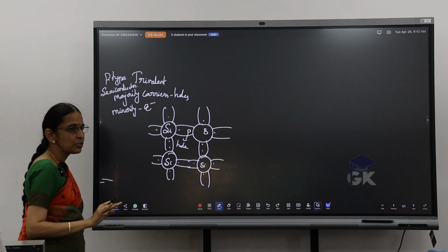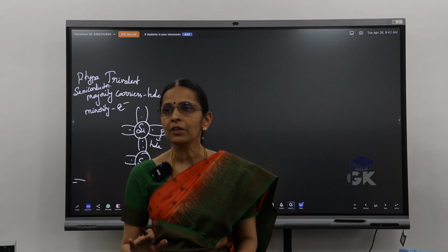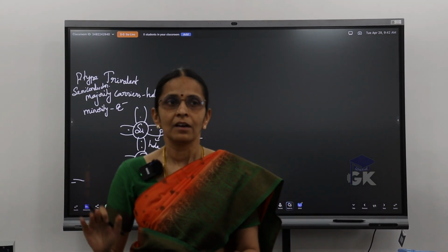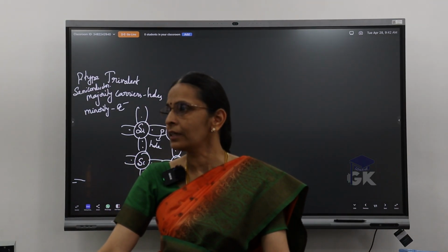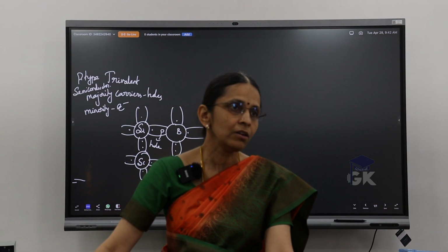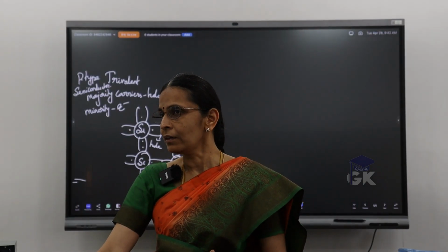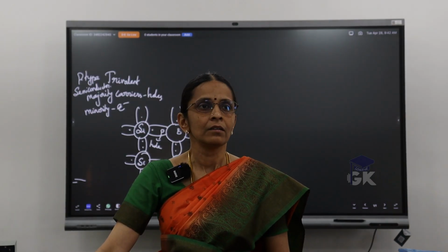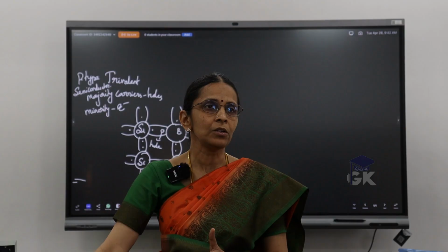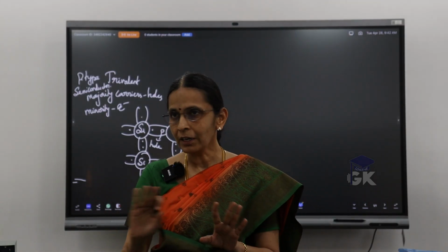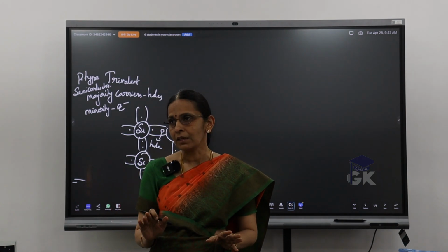So, now what's the moral of the story? If I add a pentavalent impurity to my intrinsic semiconductor, I arrive at N-type. In N-type, the majority carriers are electrons and the minority are the holes. If I add a trivalent impurity to my intrinsic semiconductor, I arrive at P-type. Majority are holes and minority are going to be electrons. So clear with this? This is the fundamental concept of forming my semiconductor material.